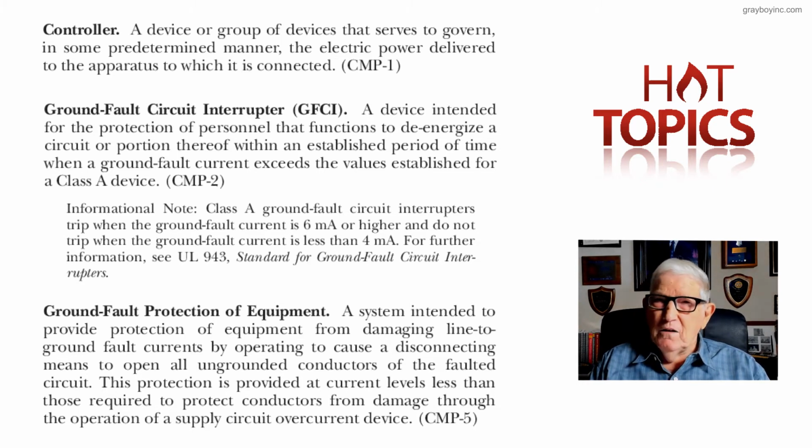Now, right now, I believe there are two things that you really need to look at. What does the authority having jurisdiction say? What is their interpretation in accordance with 90.4 and Article 100? Or maybe there is a state, county or city amendment to the NEC in relation to 210.8(F) that revises it and says, no, it's just a disconnect.